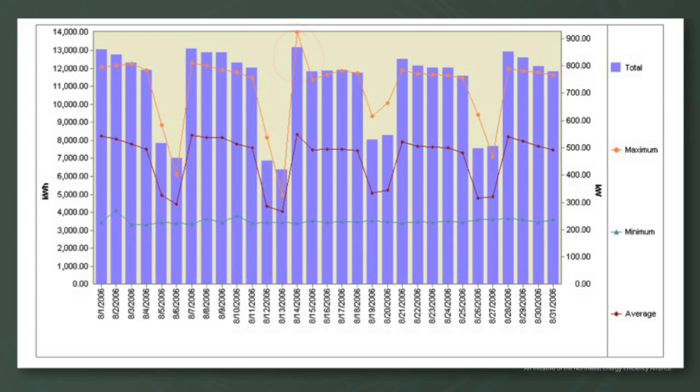If this happened just during this month, that additional cost, if you look at your utility bill, is an extra about 100 kW demand charge. And so depending upon what your demand charges are, typically between $2 and $4 a kW, this could be an additional $200 to $400 a month just because of the operations that happened that one day.